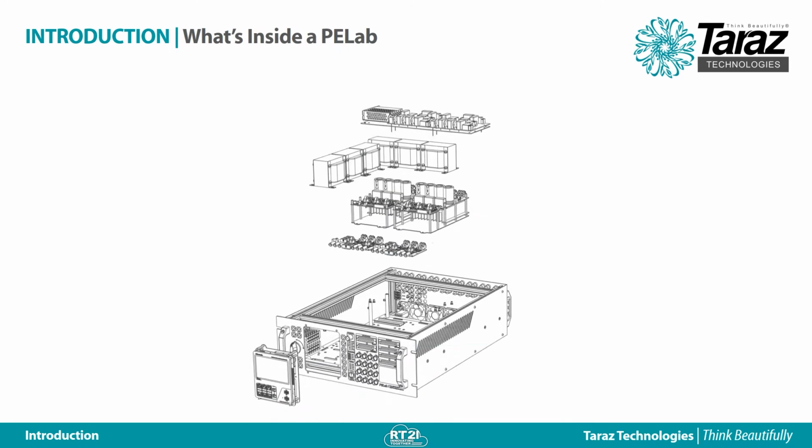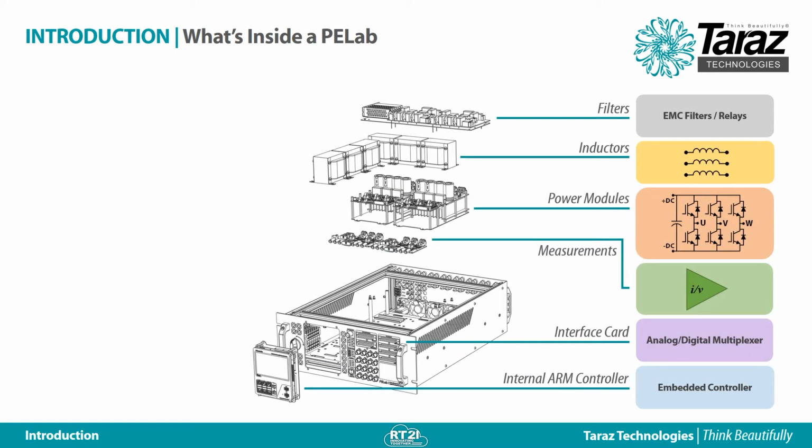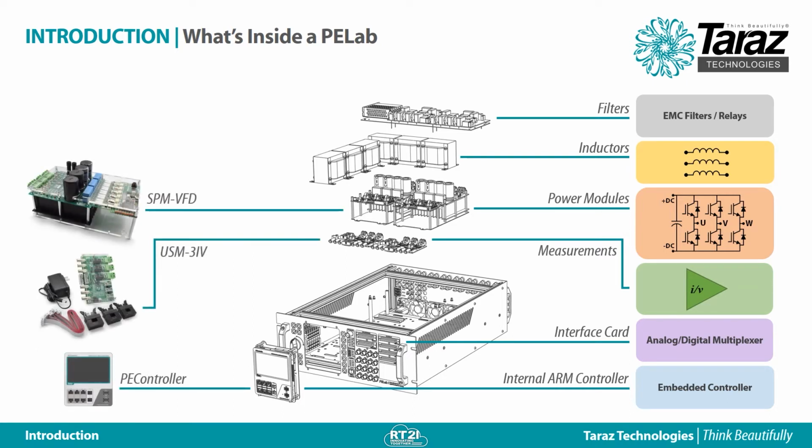So what is a PELab? The PELab is an integrated power electronics development system that can interface to multiple controllers and a HIL simulator at the same time. It includes power modules, inductors, EMC filters, relays, and all the required measurements. At the same time, an embedded controller based on the ARM architecture is included as well. As you can see, the system construction is quite modular. We use existing standalone products to build the system.